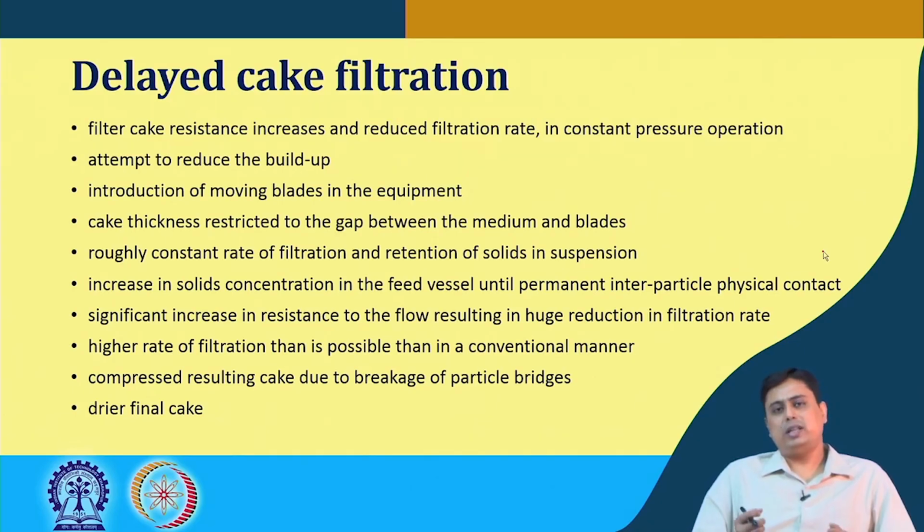until a situation appears where there is physical contact between the particles, there is no space to move those particles. Now, that leads to a significant increase in the flow resistance and huge reduction in filtration rate.